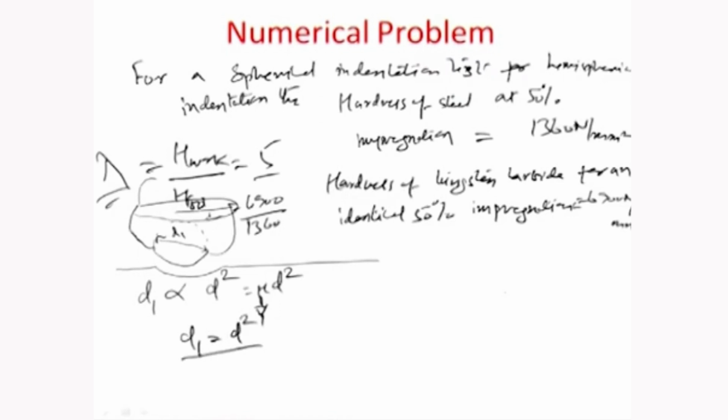So, the d1 value comes out to be equal to square of the grain diameter, and the diameter of the grain, as you know, is 0.01 millimeters. So, this comes out to be 10 to the power of -4 millimeter, okay. So, this is actually just a correlation equation. So, it is not dimensionally correct though, but then it is some kind of a correlation numerically between the value of d1 and the numerical value of the average diameter of the grain d, without looking at the dimensional aspect of it.